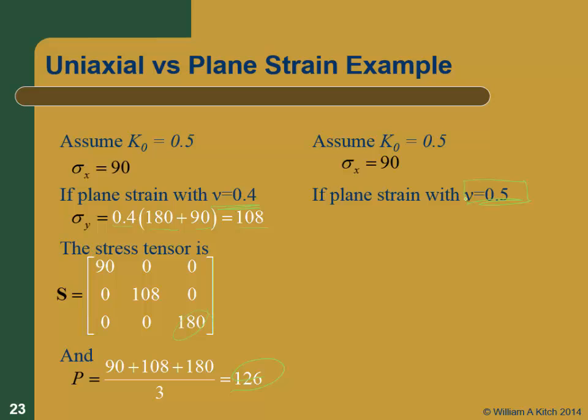So I had a dummy sample today. If I've got a Poisson's ratio of 0.5, we just said if I squeeze in the top, it's going to go out just as much as it went down, right? If it's got a Poisson's ratio of 0, I squeeze in the top, how much is it going to go out? None. Which one's going to have more volumetric strain? The one that went down and didn't go out, or the one that went down and went out some? Which one's got more strain? The one that went just down, because the out's negative strain, right? One of them's got positive strain at the top and negative strain on the sides. The total volume change is one amount. The other one's got volume change on the top but no negative volume change on the side. It's going to have more total volume change.